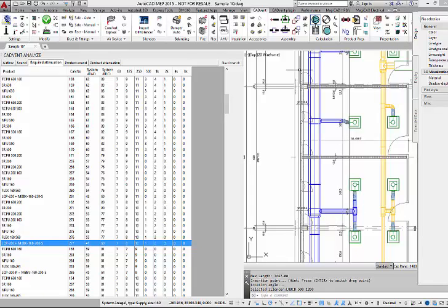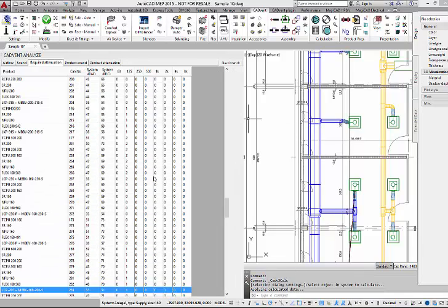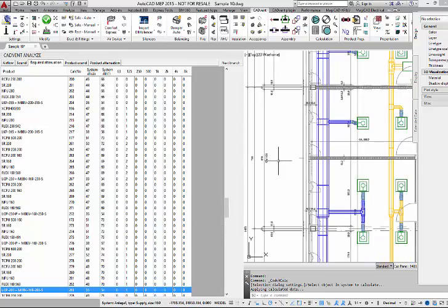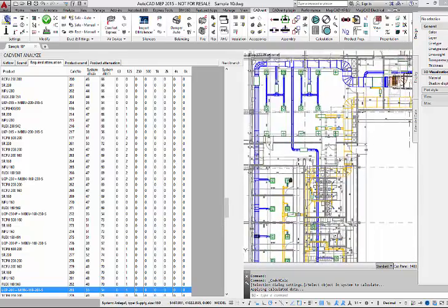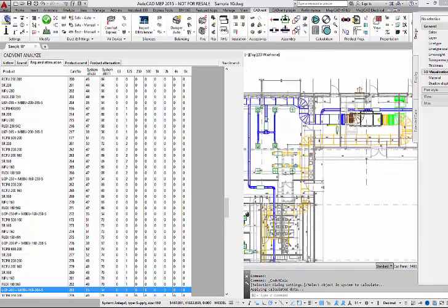And now when I make a new calculation of the system, you couldn't see it, it's on the second window now, we will see that there's just a rest information of 1 decibel at 125 hertz. So this silencer seems to be okay. 1 decibel too much, I think it's acceptable. We keep it like it is right now. Otherwise, I could have a second silencer and then we would solve that problem. But we keep it like it is right now.